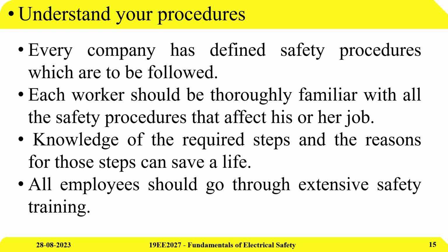At that time, if I am turning off only the EB power supply, what will happen? If I am doing some maintenance, I will be affected by electric shock. So if I am turning off the battery side also, what will happen? I will be saved. I should follow these safety procedures. In the data sheet, on the name line, on the tag line, it will be properly mentioned that we have an inverter or battery power supply, or we have a UPS system. All the employees should go through this extensive safety training.